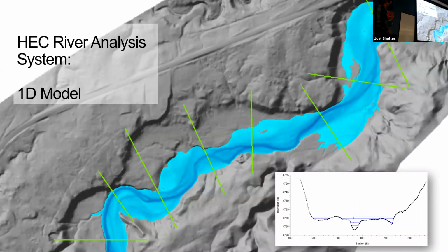So here's another example of a 1D model output, and it's confusing because this is a two-dimensional kind of flow depth thing. So this is showing depth of flow. The darker colors are deeper flow. This is just a made-up model for No Thoroughfare Canyon. Here's our LiDAR data shown as a hillshade image. And we put in a constant flow rate. And for a given cross-section, denoted by these green lines, it calculates a flow depth for a certain discharge. So I put in like 5 different discharges, and it gave me a bunch of different flow depths. So if I take that flow depth as an elevation,